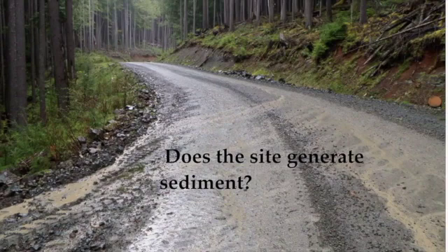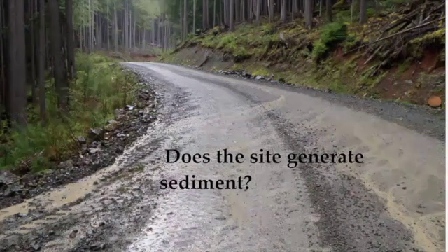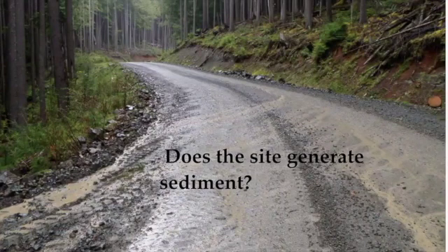You need to have fine sediment in the road surfacing material to bind the materials together. But when there is heavy traffic on it, for example, logging trucks or other heavy equipment, they pump sediment up through to the surface, and then the rainfall carries that unconsolidated material off the road. A measure of the actual erosion being generated from identified mini catchment components is the first consideration.